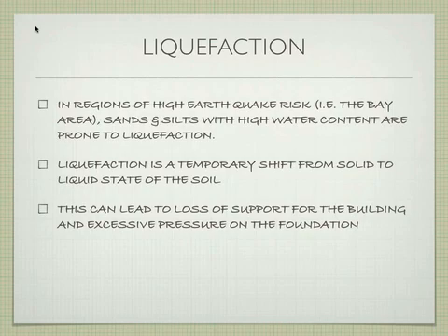And because that happens, if there was an earthquake, that particular island could turn to liquid temporarily during the earthquake, and then turn back into a solid. So if that were to happen, think about what would happen to a house or a building that was on that type of soil. It would want to sink, or go through some major period of differential settlement. Depending on the type of foundation you have, could be big problems. So this is something that does happen. That is a big problem, and people are rarely aware of what it actually is.